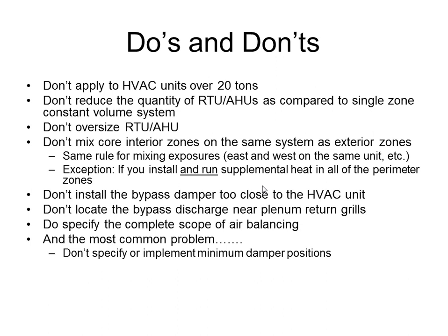Just another general rule. I hope you guys hear this more and more. You don't want to oversize anything. Most of the equipment that's out there that's not new is already oversized. Oversizing does not help unless you can do some sort of modulation, which you don't see a lot, and even still, it's not the best. You should be designing for the loads that you are calculating. When you oversize, you overcool, you dump, you stratify. You don't want to oversize any type of equipment.